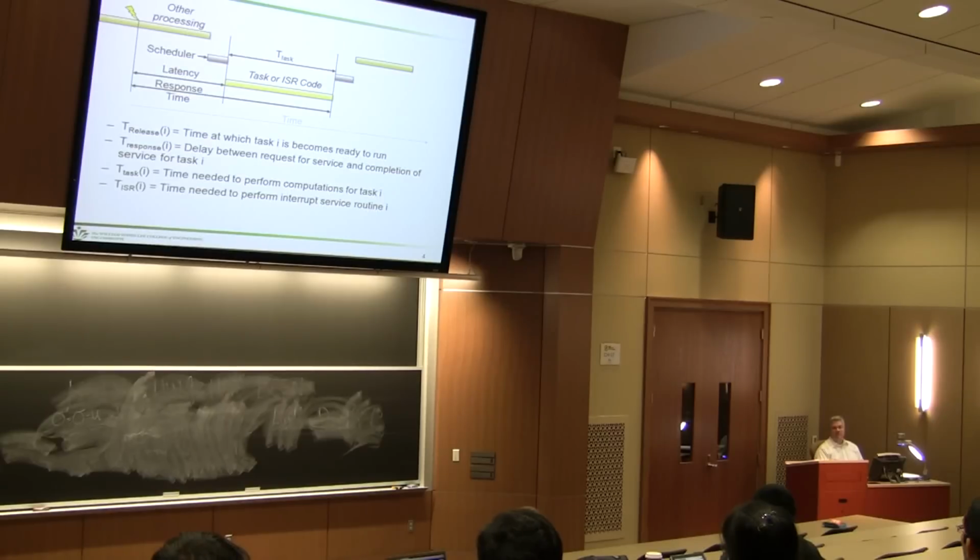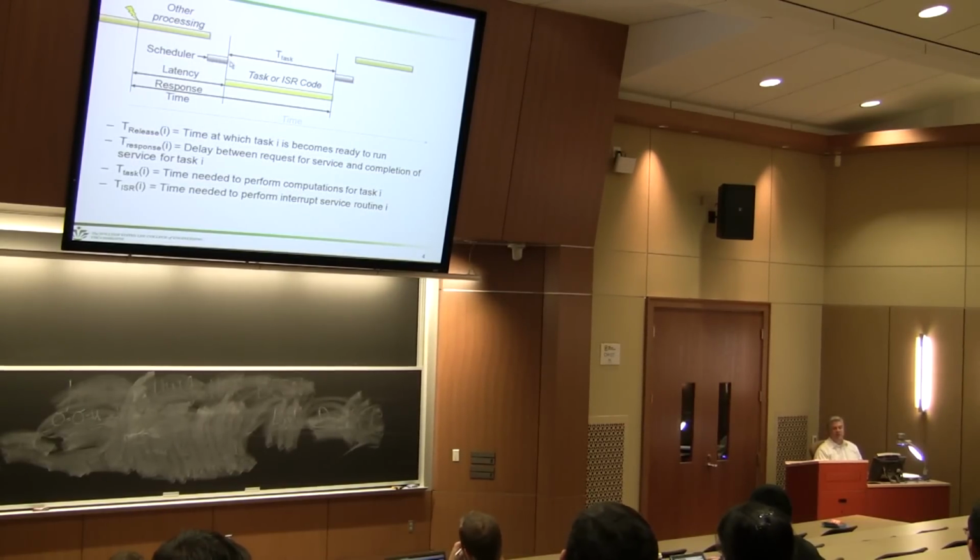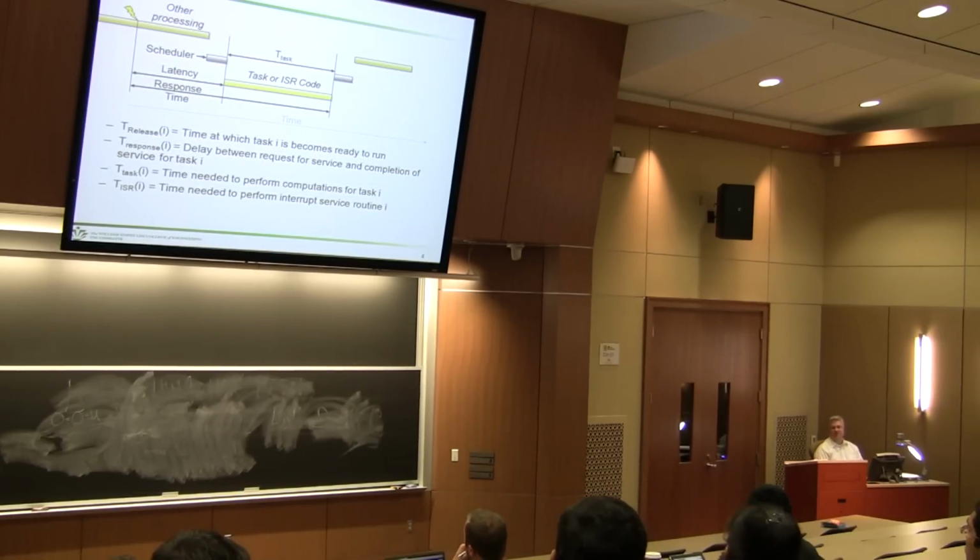So as you can imagine, would it be good to switch really frequently between tasks that need to run? I mean, like really frequently. Well, if you have a certain amount of scheduler time that needs to run every time you do what's called context switching, whether you switch from this process to an ISR, there's always some overhead associated with that. Obviously you want to reduce the amount of overhead that the scheduler takes. This is the amount of time that it's saving some registers, that it's saving some data, because you're going to change what's running inside the machine.